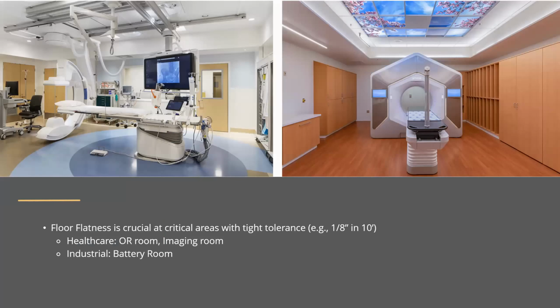The other use case that we find to be very helpful is at some critical areas, like imaging room or OR room. For these critical areas, we would typically have a tight floor flatness tolerance, like 1/8 of an inch in 10 feet, or even less. The floor flatness analysis can be used as a QA/QC tool to ensure the high quality of the final product.